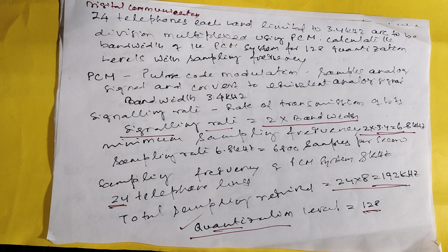Then what is the sampling rate? As per the Nyquist theorem, the minimum sample rate for the highest frequency that you want to measure, the Nyquist rate, is 2 into the given frequency to be measured.